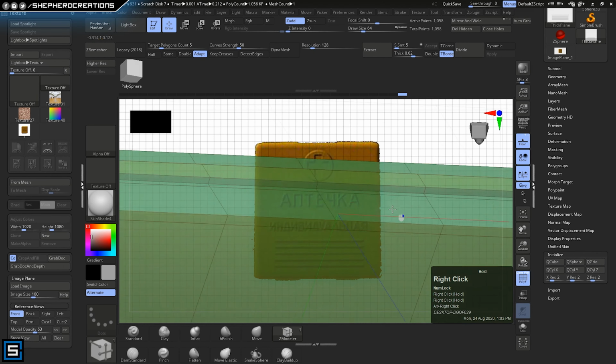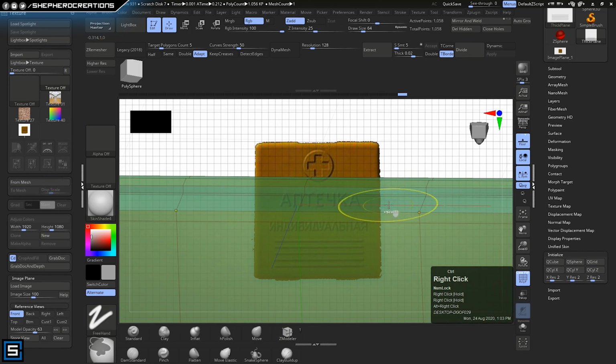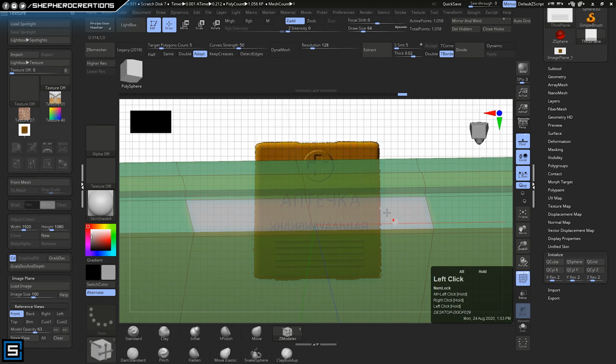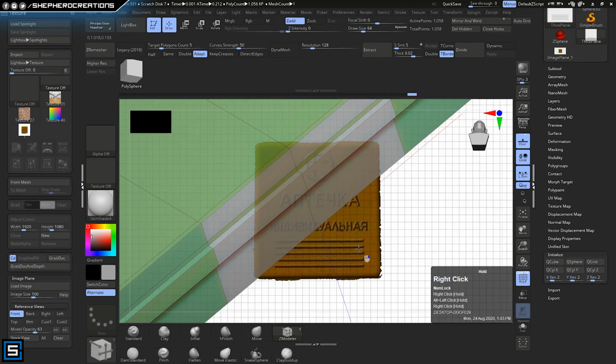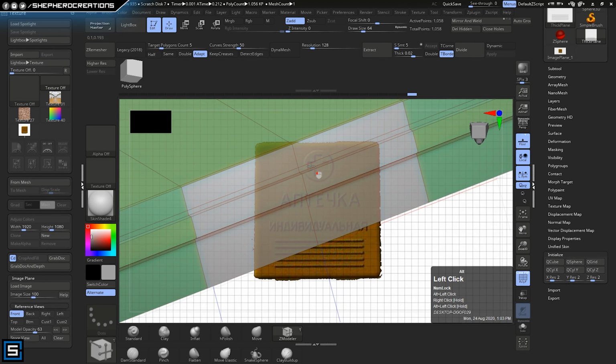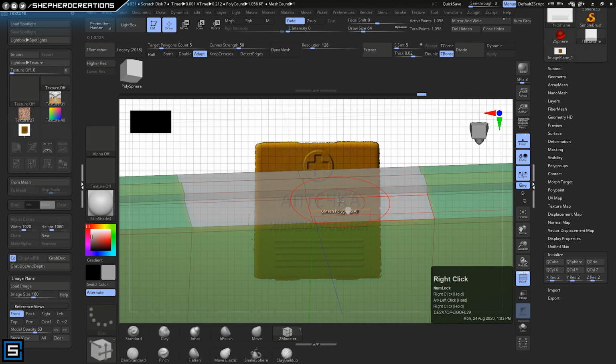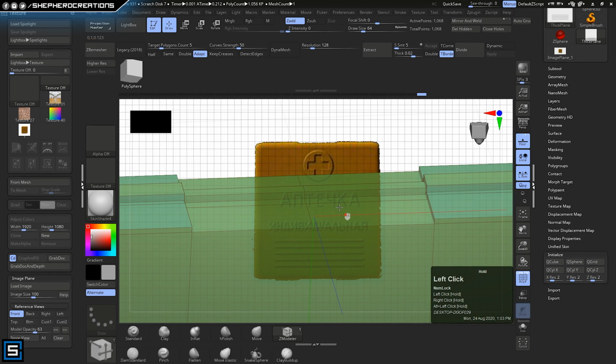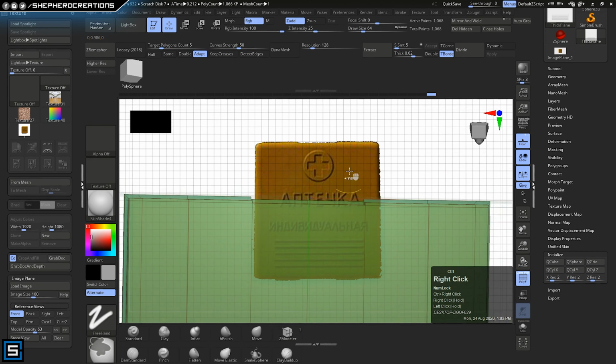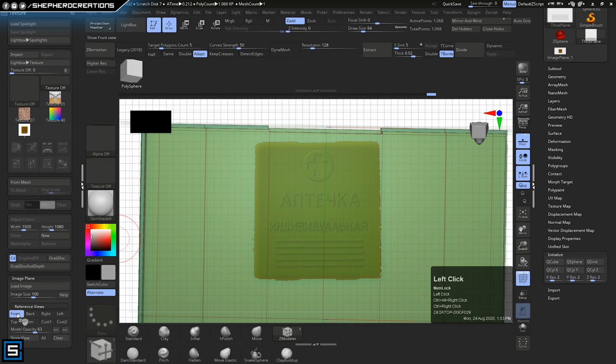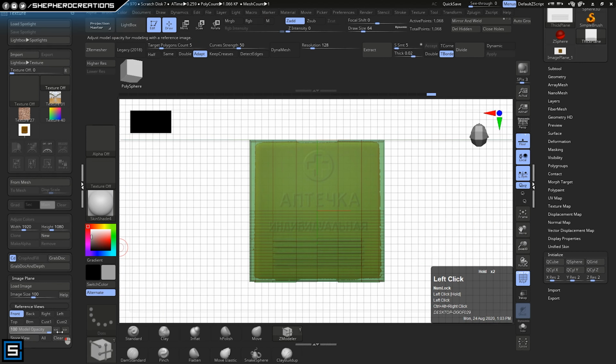Now what I'm going to do is, I've got an indentation on the top part above this medical cross, and I'm going to highlight a new point and squish that back down, I guess a negative extrusion, so that I can get the overall shape of this object adjusted. Now you can see that I created a limit with that new poly loop, and then I highlighted that area and pushed back into the model, and it completely removed it.